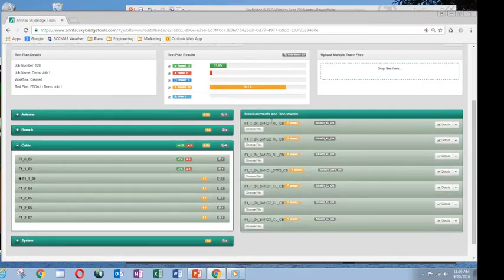At any rate, if I look in here, I'll find I have 7 tests for each cable. I've chosen to do a band 1 return loss, a band 2 return loss, a band 3 return loss, a band 1 DTF with a short on the end, a band 1 cable loss, a band 2 cable loss, and a band 3 cable loss. Exactly what you do with this depends on the requirements of the work you're doing, on the MOP, on the statement of work. What I've chosen to do here is typical and something I've seen in past jobs, okay?